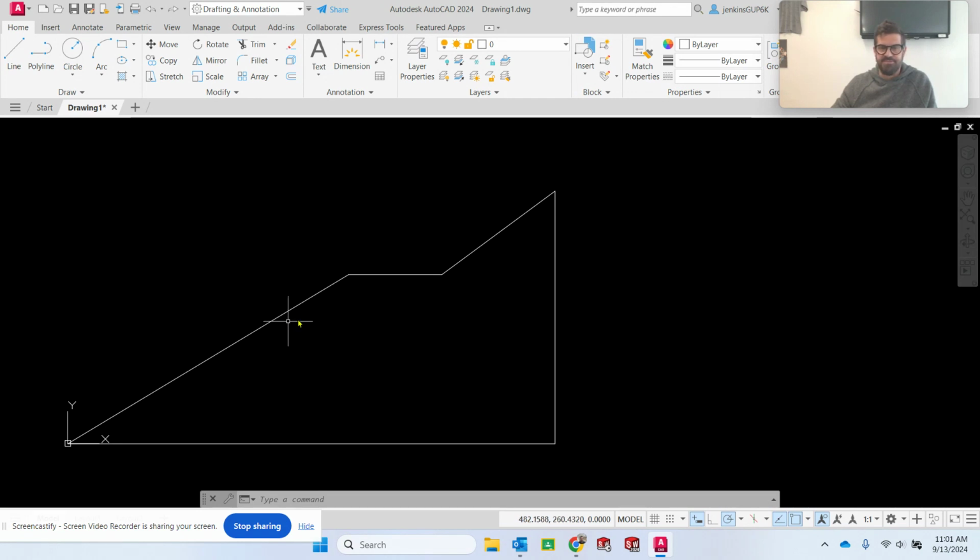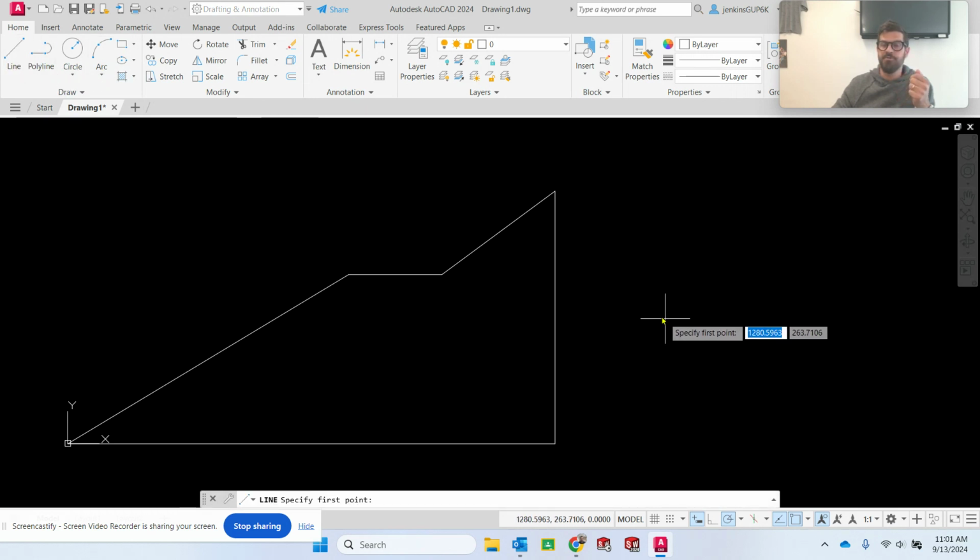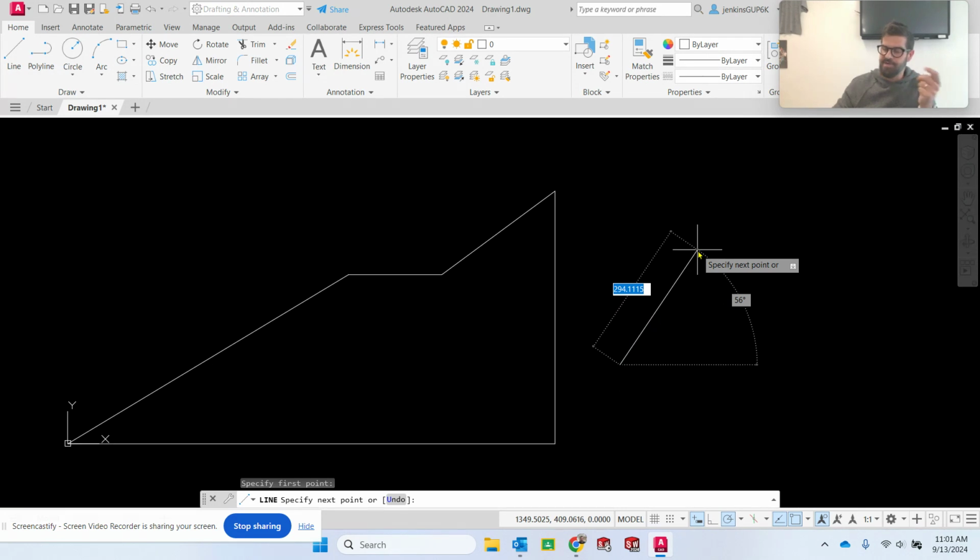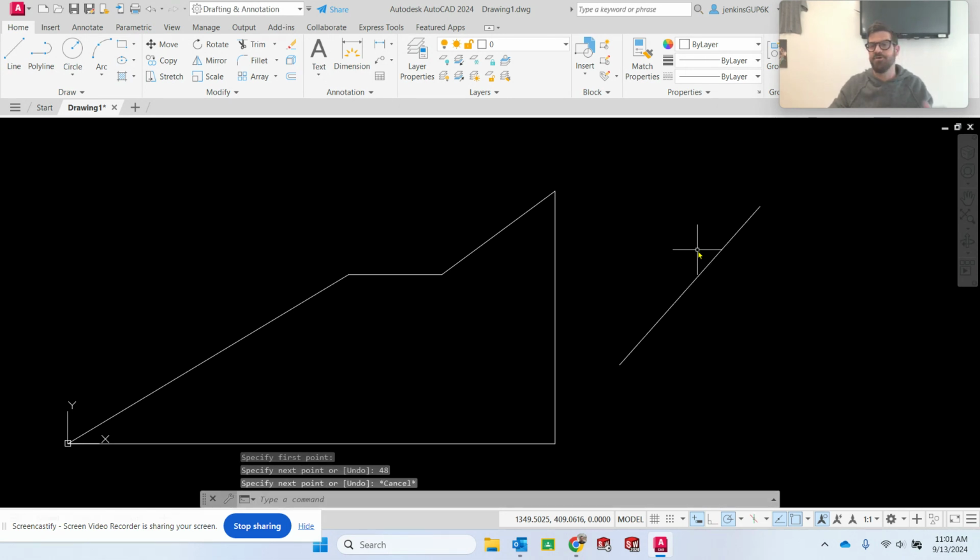It's a whole bunch of, it's several lines. I've showed you how to lock in. Let's say if I want to just draw a new line and I want to make it 200 units long at a 48 degree up from the horizontal angle. So if I click starting point, what did I say? Let's say 450, tab, 48, enter, and it has now drawn that line.